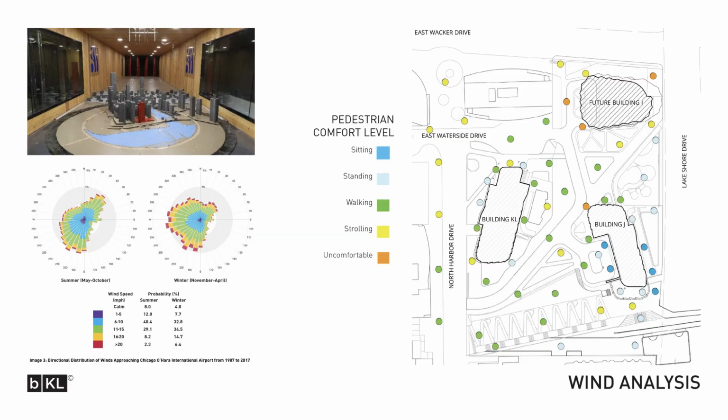For the wind tunnel analysis, other than the ones that are done for structural considerations of the towers themselves, we performed the ones for cladding of the building, so that the cladding can be engineered efficiently and to the anticipated design wind loads that are specific to the local context.